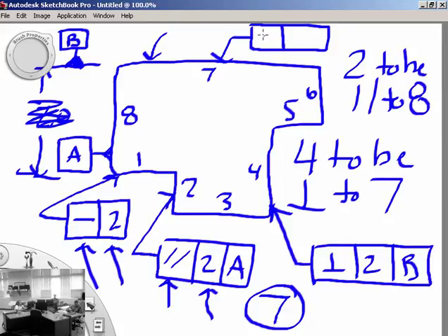Tolerance size is 2. Now, little side note, sometimes you'll see datum references here for no apparent reason. Flatness tolerance is really about how much the surface deviates. So likely you're not going to see a datum reference, but it's possible a designer could throw it in there, but not super relevant if they do.